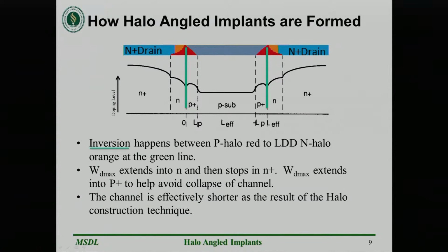Making heavier doped regions at particular points on the channel length helps adjust the amount of needed barrier to control electrons to pass by, and to maintain the threshold voltage on the edges of the channel, improving VT roll-off.